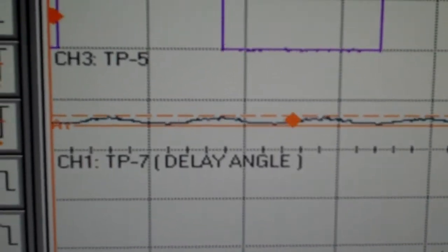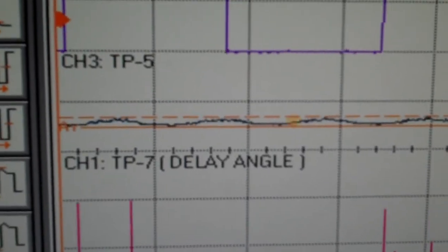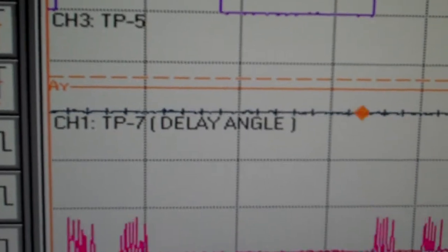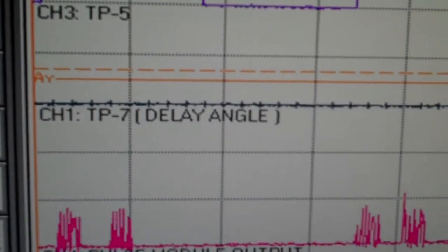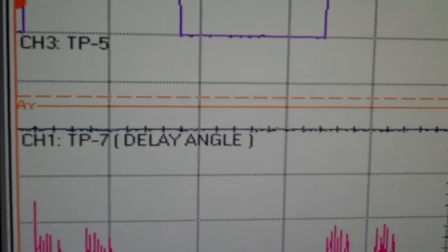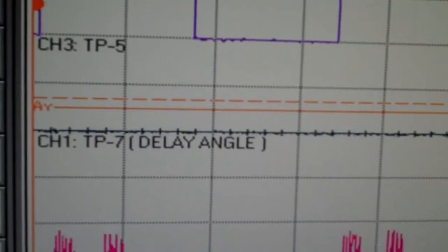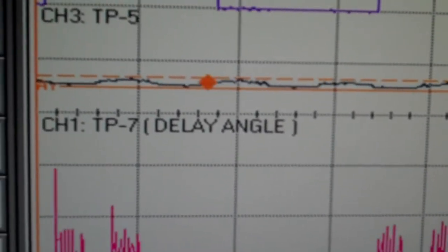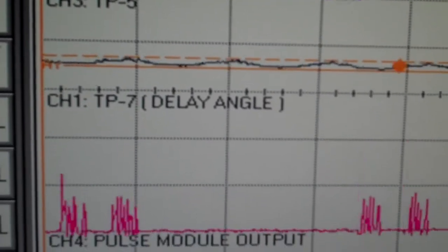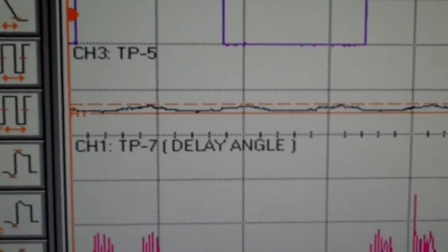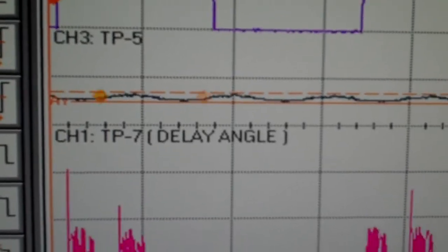Now we're going to go to TP16. TP16 is the same. It's the resulting reference signal from the Y bridge, that is also going to be compared against the threshold. So there it is. If under these working operation conditions the resultant signal is not within this threshold, that's when you have a phase loss.